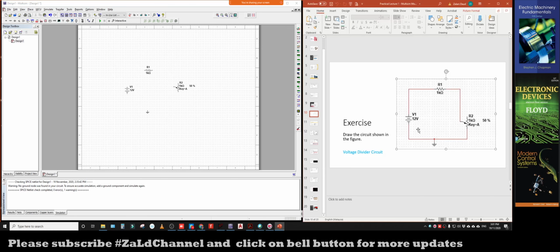So next, I'm going to place the wiring. To do the wiring in Multisim is simple, not like LTspice. In LTspice, I have to click on one of the components, which is the wiring component. But for Multisim, you just move your cursor to the point, which is one of the terminals of the battery, then click. So you can do the wiring like that.